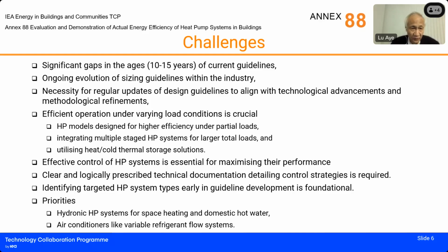And if we are looking for better energy efficiency for heat pumps in buildings, control is a very important one. Lawrence already mentioned it in his presentation. Depending on how you control it, how you defrost your system if it is air source, these are very important aspects for maximizing the performance of our heat pump.